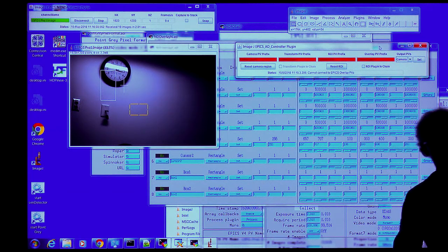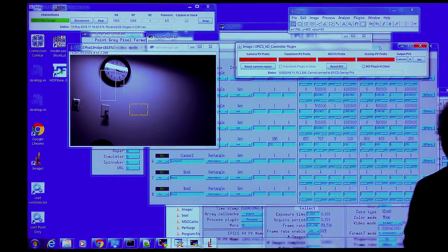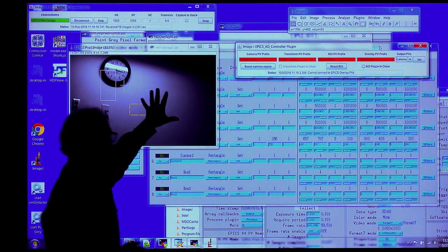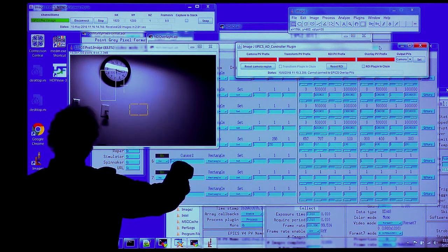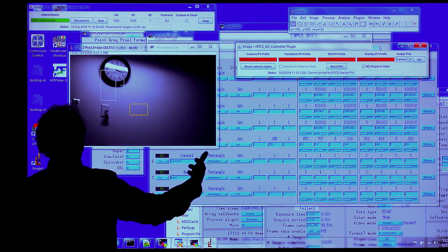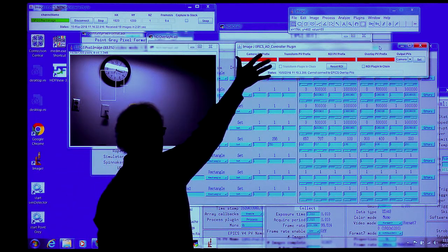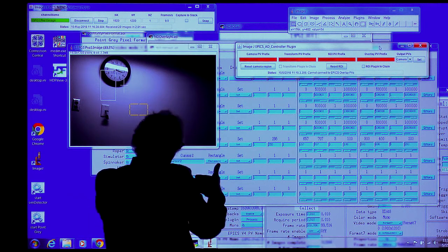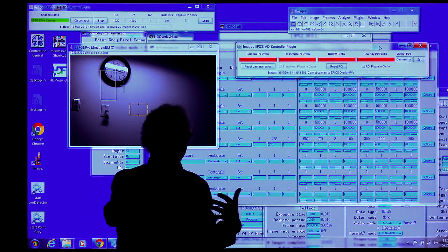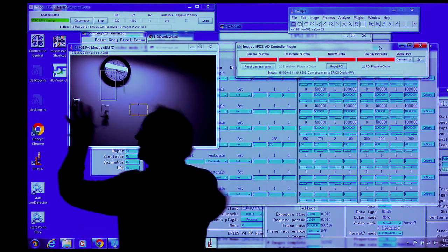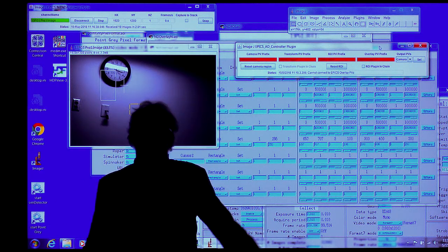Any more questions? Everybody's hungry. Very simple one. Can you keep the image mono, but say you wanted to change your rectangle and make it red? Is it possible to do that? Yes. You need to take the image from the camera and put it through a color convert plugin that changes it from mono to RGB. Then this works on the RGB image, and so now you can make this red and green and blue. It does mean that downstream of that plugin, you have 3 times as much data. You probably wouldn't want to run that to your disk file, but you can run it to the screen, so that the cursors look nicer because they're in color.